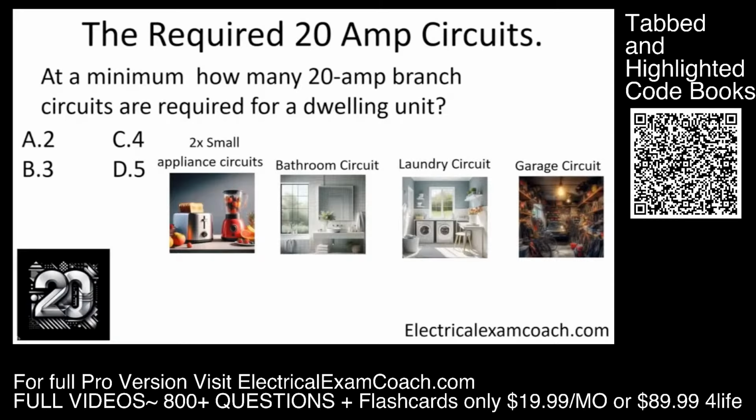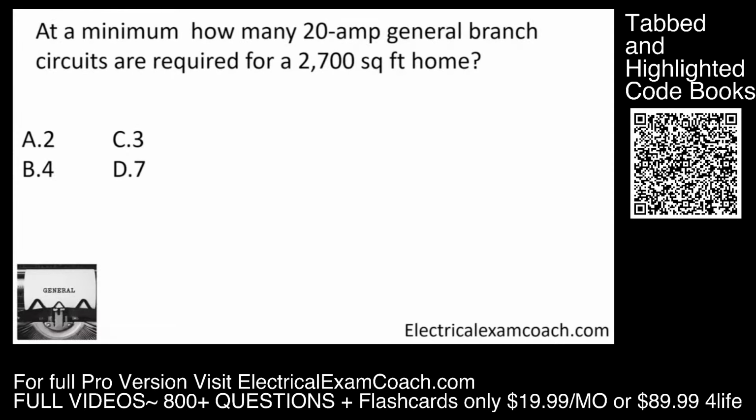Now, this is not to be confused with the type of questions that are asking about general or lighting or receptacle circuits. These are the code minimum of the required 20 amp branch circuits in a dwelling. And the answer is 5. Great job. At a minimum, how many 20 amp general branch circuits are required for a 2,700 square foot home?